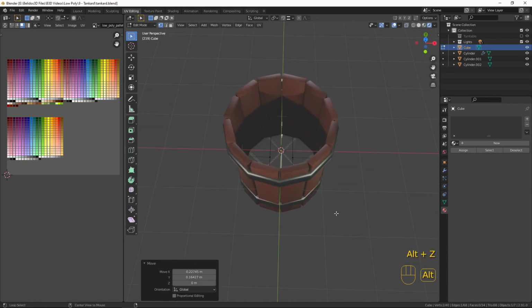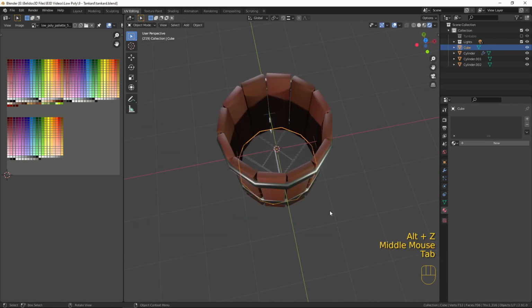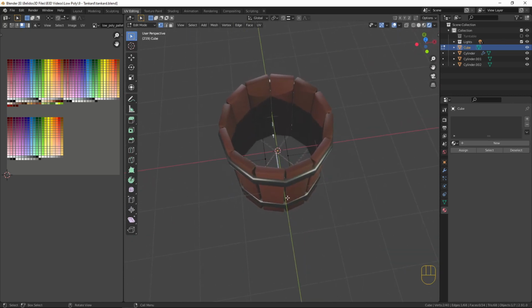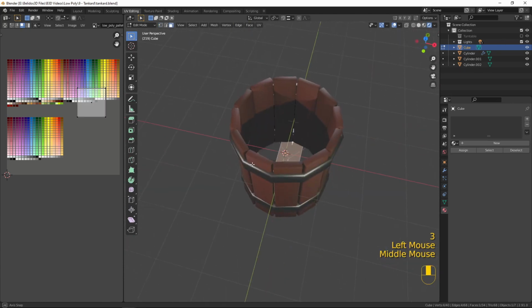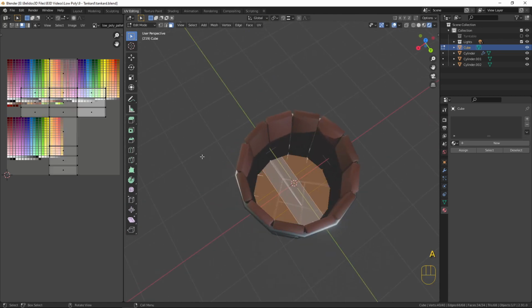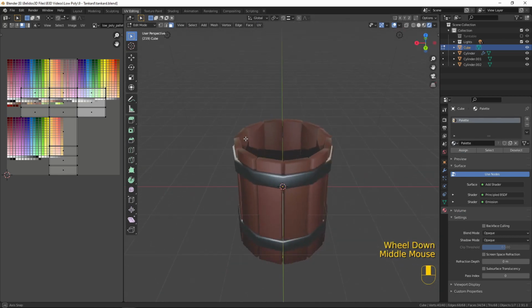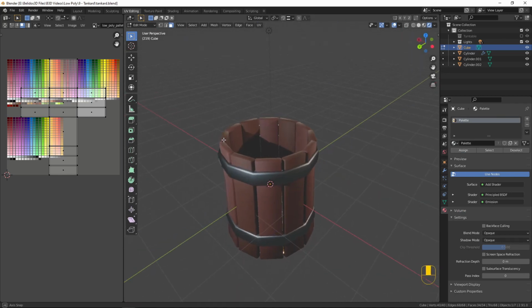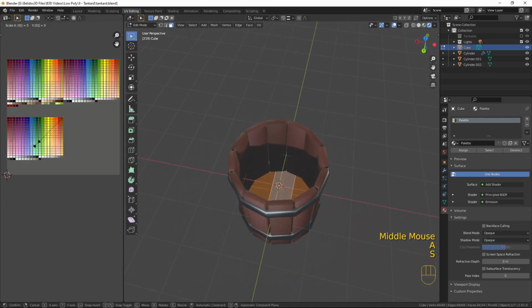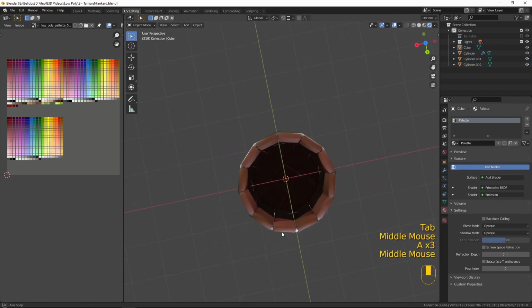Okay, let's come out of X-ray mode and let's have a look. And everything seems to have disappeared. Oh no, it just seems to be really see-through. Okay, let's give it a texture. And U and R, A, S and 0, and we will give it the wood colours just here. So that brings that out like so.